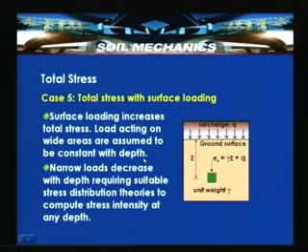Suppose the load acts over a wide area, something like a wide area fill, for example over an existing ground level, say if you are reclaiming the ground. That represents a wide area fill over an existing ground surface. In that case, the entire stress is transferred directly to the soil mass. It is something like a stratified layer which is coming above the existing ground surface of a given soil site.